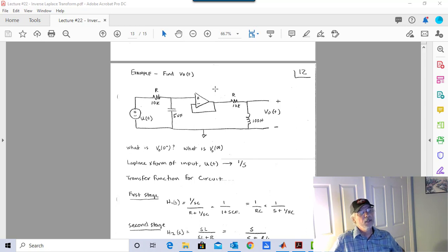But really important that you know why voltage buffers are there. They sniff this voltage, and then they produce that voltage right here with no Thevenin output impedance out of this op-amp. If you're taking EE330 or your introductory microelectronics class, kind of like an emitter follower, isn't it? The emitter just follows that base 7/10 below like a little dog. So it's a voltage buffer.